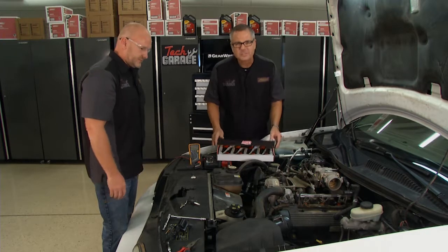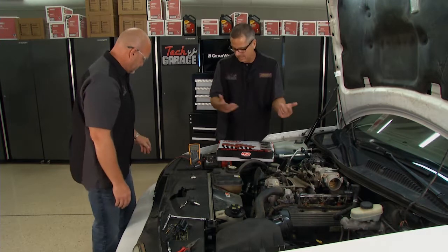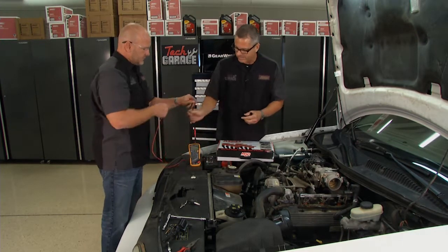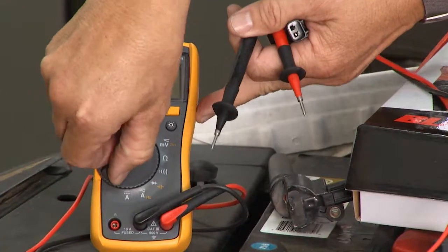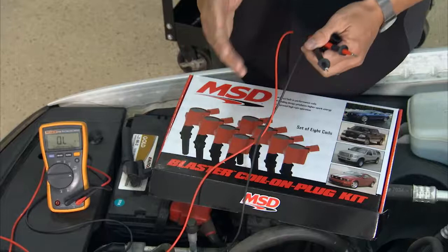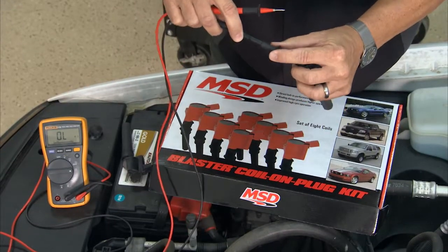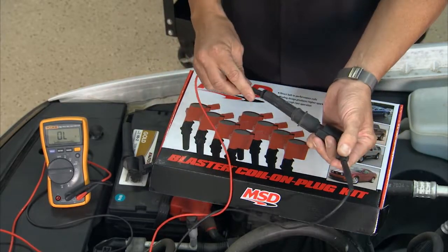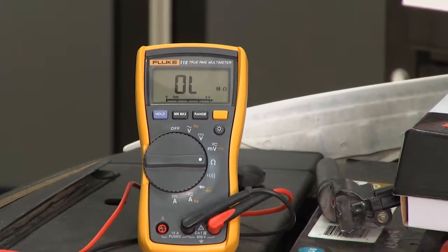Now, a couple other tests you could make. Maybe you don't have access to the coil like Brian had, the other coil. So you can pull that coil out, which is the bad coil, and you can take the meter. You got a DVOM, you can go right in the garage and do this. Take your DVOM. We talked about earlier, the primary and secondary sides. Well, you can come across the secondary side by going to a terminal. Once I get touching that terminal, and I can come down to the bottom here. There we go. All right, it's showing about 5,000 ohms of resistance.